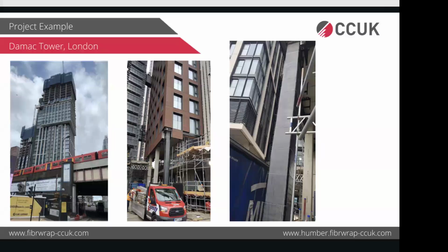So they asked their on-site contractor to cast another concrete jacket around it. They said it can be done. It will take 2 weeks to do the work, and after that 28 days for it to cure. They did not have that much time because the bridge was already in transit and there is no way they could store it on site. So we did the strengthening using carbon fiber when it was feasible.